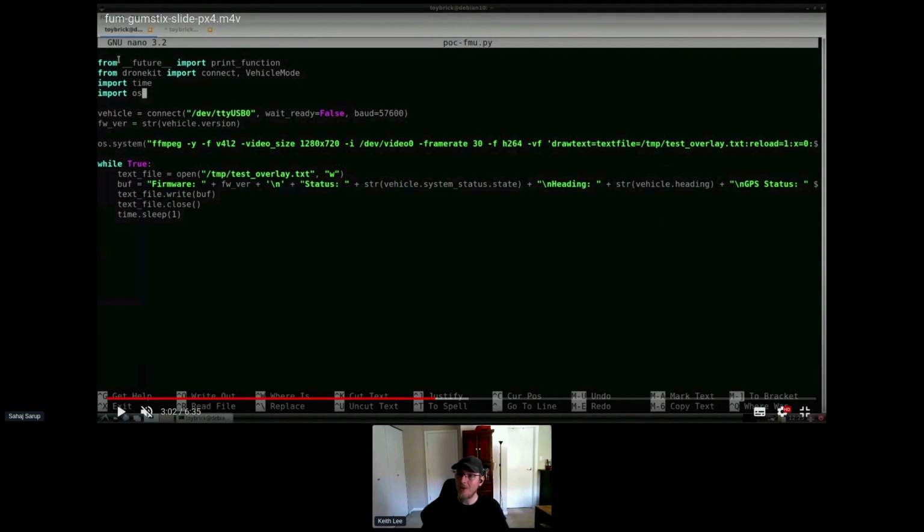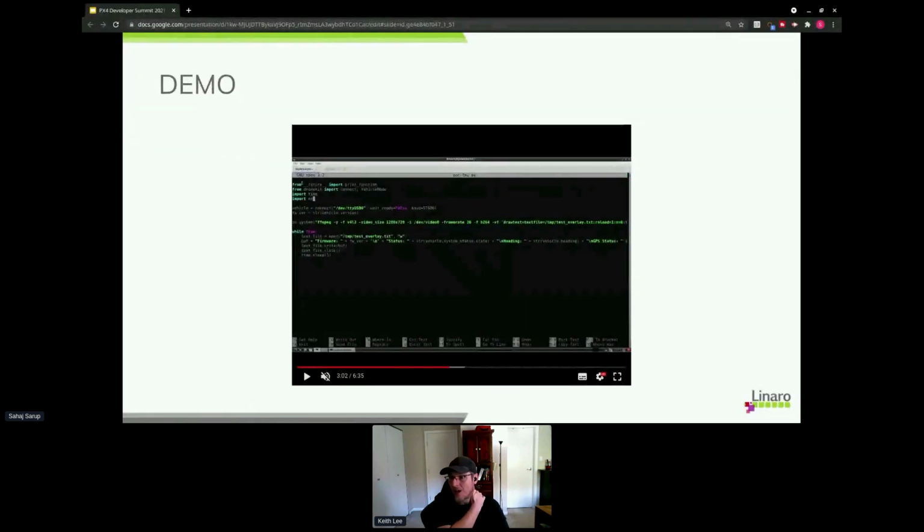There's just one question I wanted to address before we close. Yeah, thanks, Brent, for asking. With a lot of the high-speed signals, I understand your concern about wanting to make sure there's enough room for routing. With a lot of the high-speed signals, you'll find that there is a path that extends from the source of the connection to the sink, and it'll indicate in green if there's clearance, or if it's within the constraints of the signal, or it'll come up as red if it's blocked or if it's too far away from the source. That is one way we handle high speed.